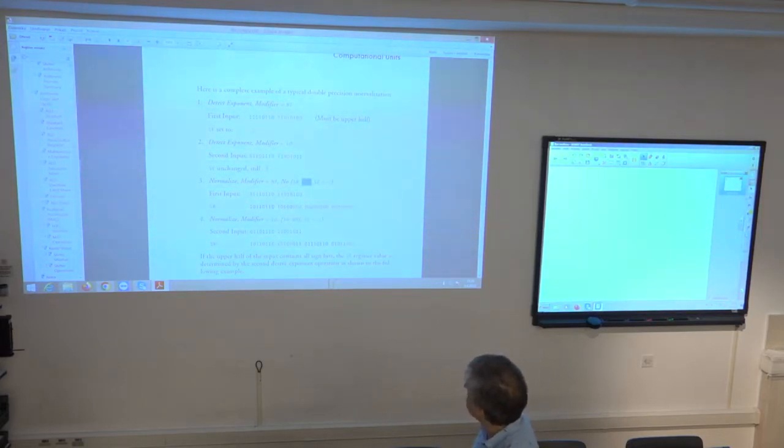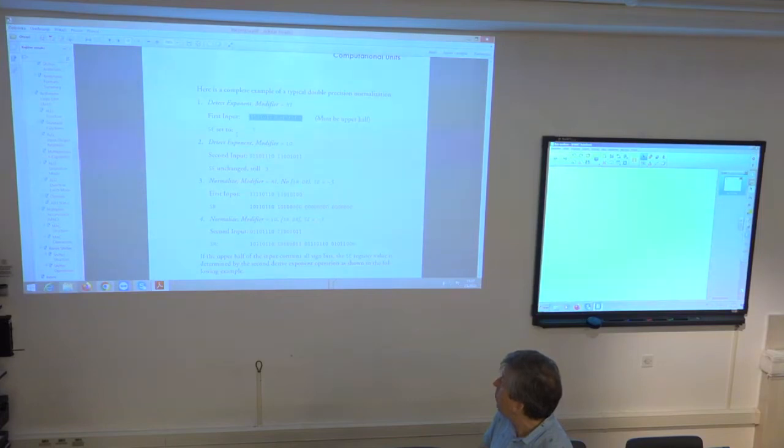For example, I first take the input, which was 32 bits. So you have the upper word and the lower word. And then you perform the first instruction to detect the exponent of the upper word. In this case, the upper word was this. So again, I have 3 ones that are excess. Again, they've set this value to -3 after the execution of the instruction exponent of the input value, that is the upper word.